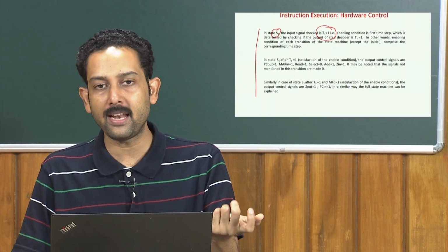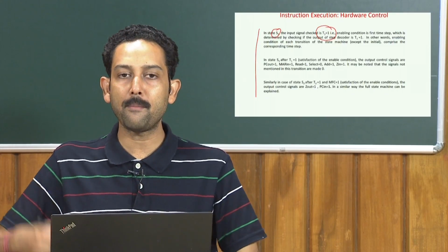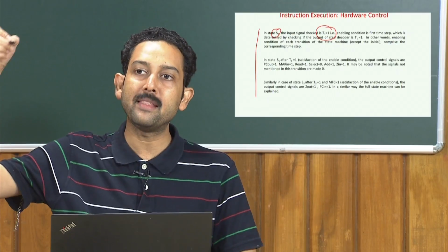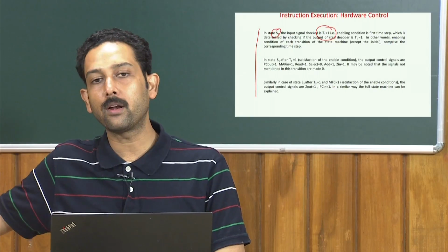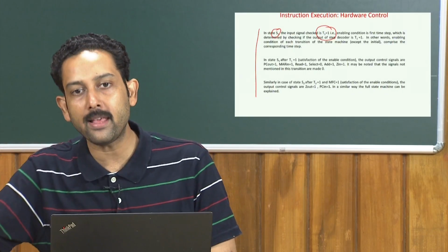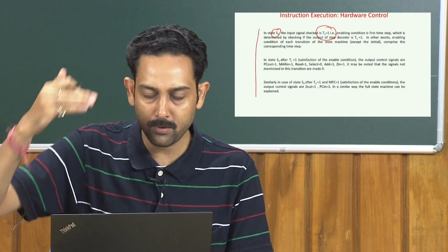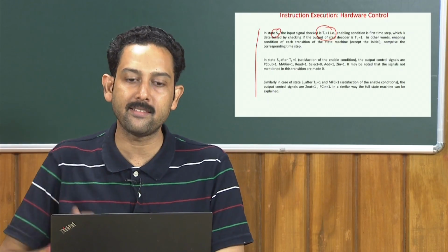Whenever you want to implement a finite state machine, remember that you always have to increment the states, like 000, 001, 010, so you have to generate the forward counter. Only then can it translate into a sequential machine that the states will go through. This is just a simple digital design fundamental.